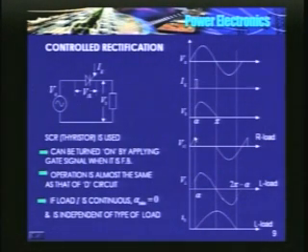So this is Vi. At omega t is equal to pi, it becomes 0. Input voltage is also becoming negative, so voltage across it also becomes negative till 2 pi and the cycle continues. This is for the purely resistive load. Average value we can determine by integrating this waveform.